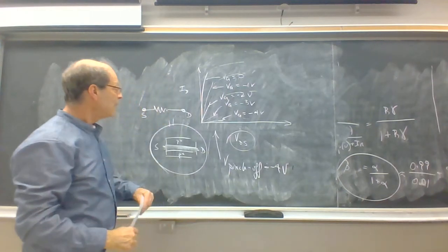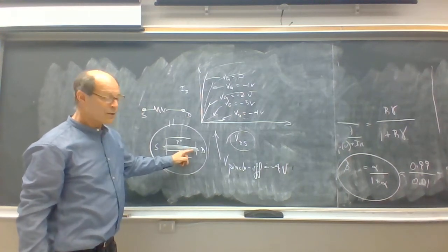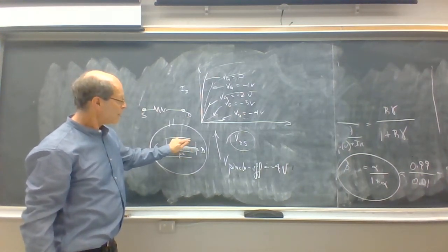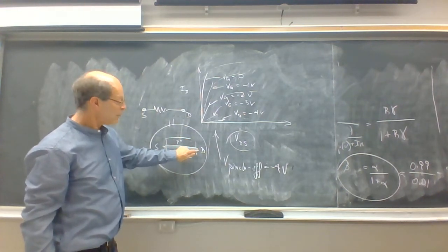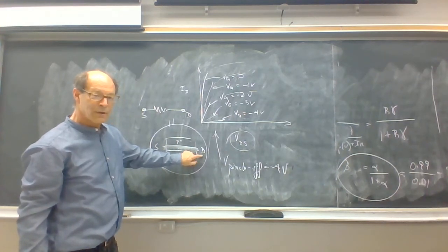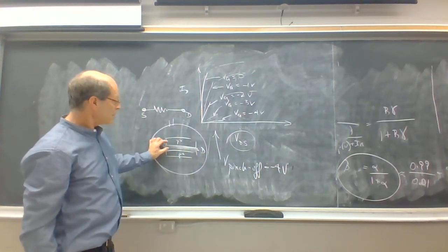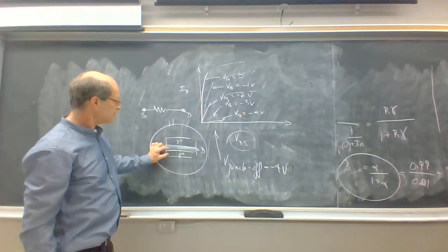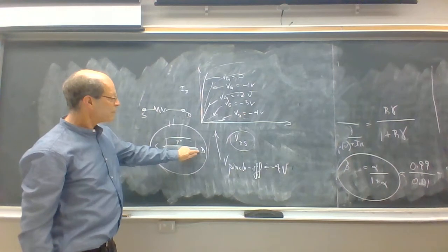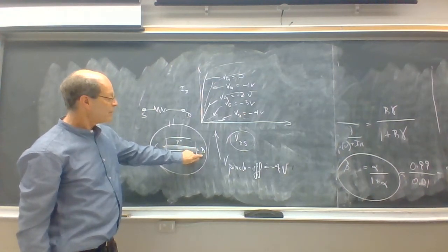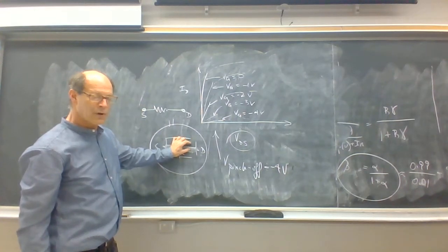And what's happening is that on the drain side of this device, the voltage drop between the gate and the channel depends on the voltage at the drain. So that's a very different situation. You can't expect the drain side to behave the same as the source side. So as the drain voltage goes more positive, the channel is going to move toward pinch off on the drain side.